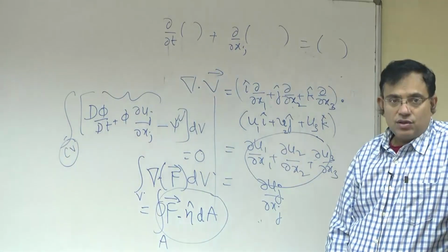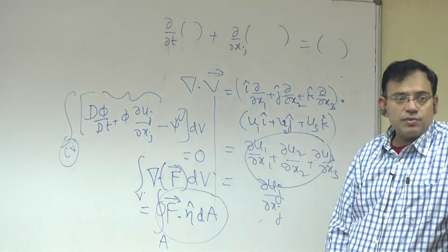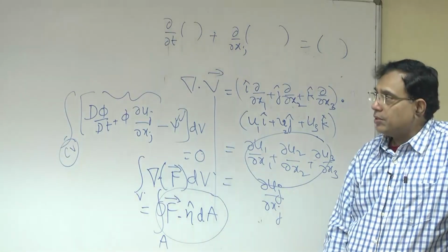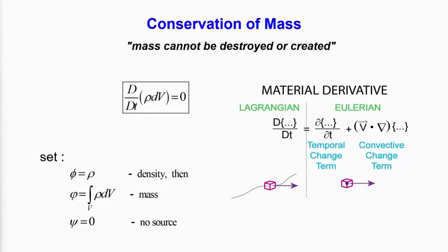Now, mass is defined as density times the volume. So, when you have mass conservation, think about a packet of mass, that pink colored small element. Say it has a density rho and volume dV. So, its mass is rho into dV, and as it is moving, described by Eulerian coordinates with its velocity etc., its total derivative of mass is 0.